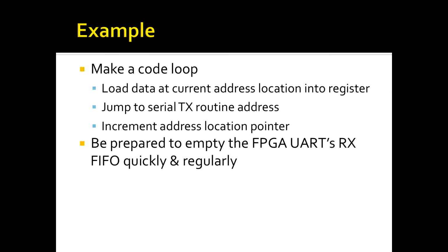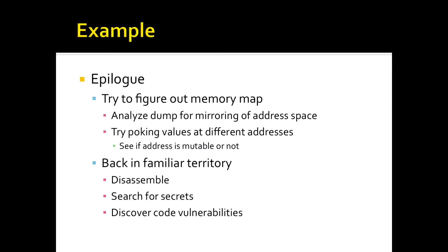And you have to be prepared to empty the FPGA's receive UART buffer quickly and regularly, because basically the entire code and data space in this particular chip will be dumped out in an endless loop. It'll just keep mirroring and wrapping over the address space, and this is kind of what's known as linear code extraction.